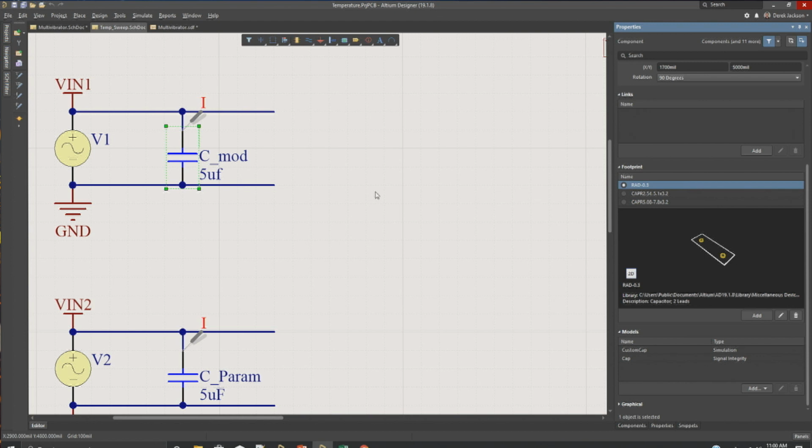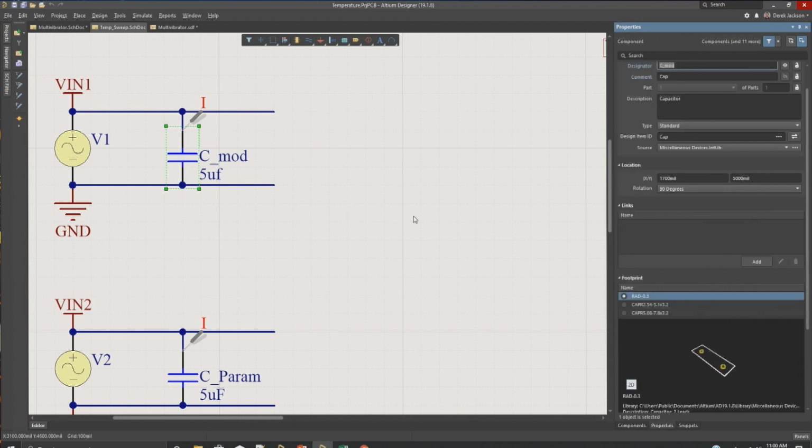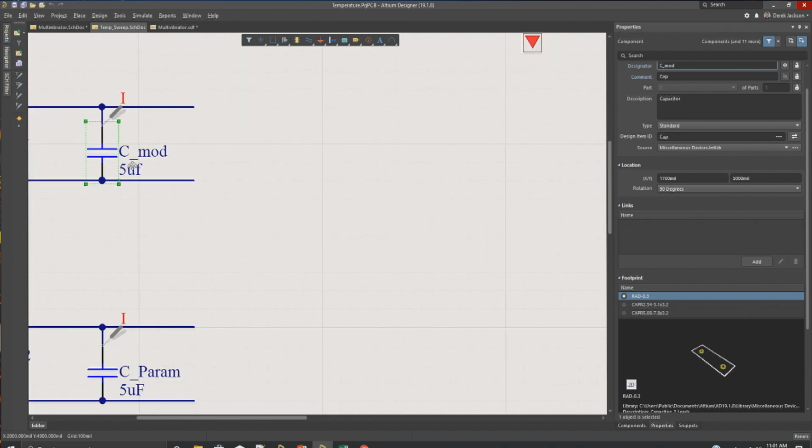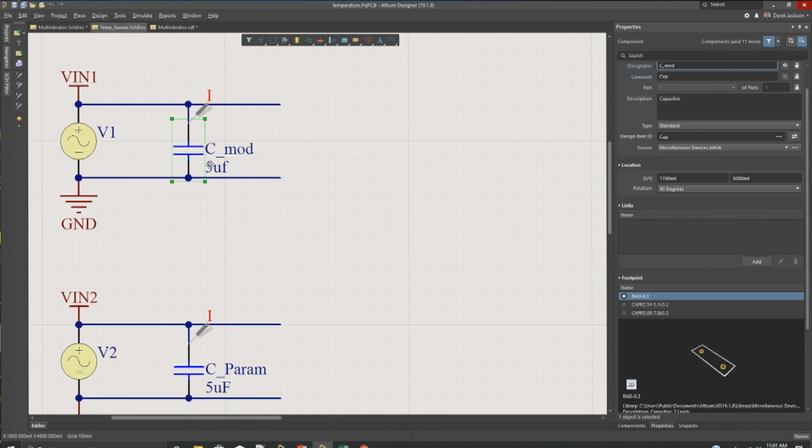The majority of the time, if there's a PSpice model that's not encrypted, you can download and use it. And for capacitors, there's no voltage variation, or do you support that? Now, in the downloaded examples there's a voltage multiplier. There's a temperature example, and if you download the circuit sim, there's a PSpice one that does have the voltage modifier which Microsim and PSpice had added, but the new ngSpice doesn't. It doesn't have the voltage multiplier or the value on the capacitor, so that might be something we add in.